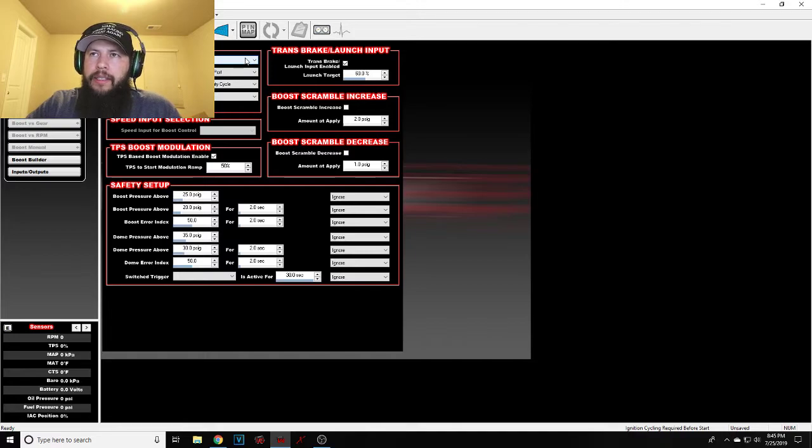I'm telling it single port wastegate type, and the solenoid configuration is a single Holley 3-port. I'm using a 4-port. It honestly doesn't matter. It's going to operate that 3-port the same way it would operate the 4-port. As long as I have my base table pretty close, it's going to be able to fill in the gaps really easily. You can't lean on it completely.